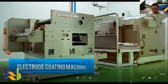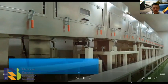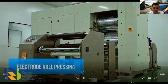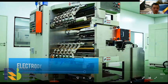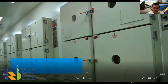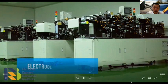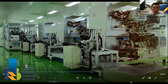This is coating. We have 2 lines. The oven product. And then this calendaring or roll press to get a good connection. And then this slitter divides the anode or cathode. After that, we need to dry again to avoid water inside the cell. Then we do the welding for the tab, for the polarity, negative. We go through the winding machine.